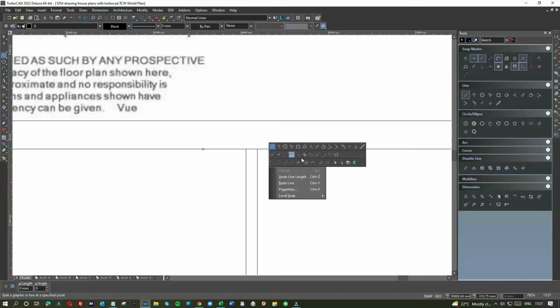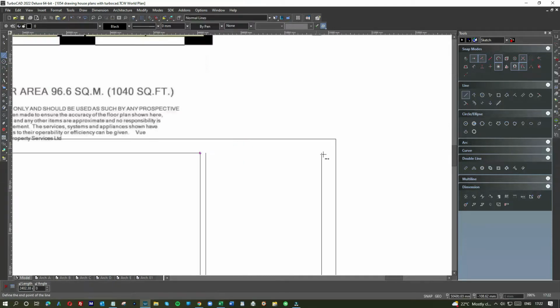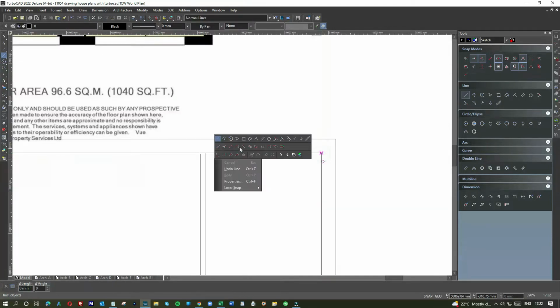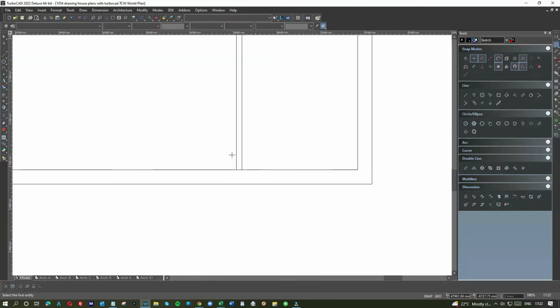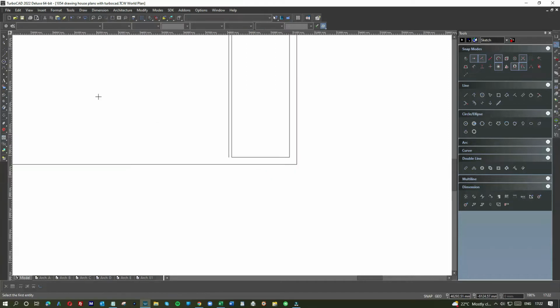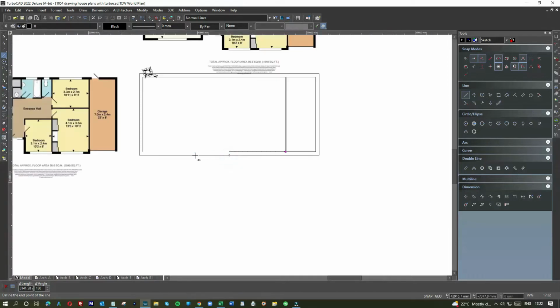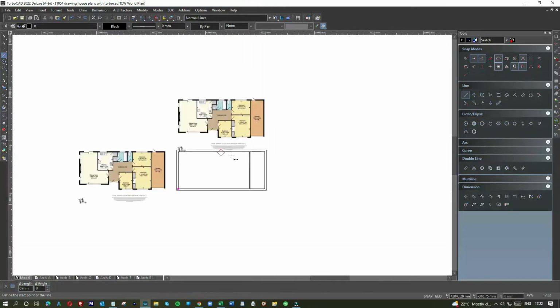So now watch what happens when I use the meet two lines. Yeah, you lose the line. I take from over there, then I use it again. Meet two lines. If you get used to using the meet two lines tool, as against taking the slower route, it'll be a real time saver in the end. Okay, so you can see we're getting there.